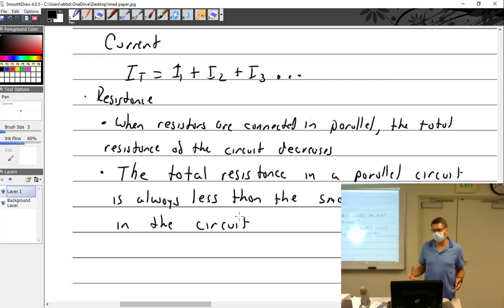When you're doing these circuits and you're looking at stuff, just take a look at what you got. That's what I do when I check you guys. I was like, okay, well, the smallest one right there is a 10, so it's got to be less than 10. I look at your sheet, it's like 60. I'm like, well, you made a mistake. They're like, well, how do you do that so fast? That's all I'm doing. So if we're computing it and we realize that our total resistance is higher than our lowest resistor, then you made a mistake. Start from square one. Start again.